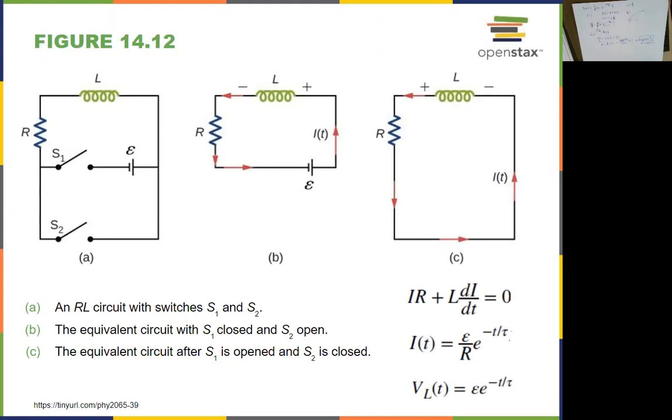So this is something similar to the RC circuit you guys did in the lab. If you have an RL circuit, so close the switch S1, but keep this guy open. Then in this case, instead of charging the capacitor, you are now building current up in the inductor. Because this is open, we do not focus on that. So current is building up on this guy. After some moment later on, you'll have current equal to epsilon over R on this inductor.